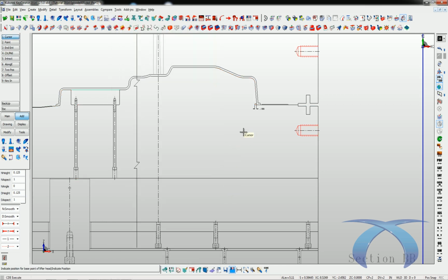So then all I want to do is give a general area where I want the bottom of that lifter to be, right? I can use my snap if I want to make sure things are nominal. It's totally up to me how I want to do that. Then once I'm happy with my location, I just push OK. And then which direction is my rod going in? Is the rod going in this direction, or this direction? So it's going in this direction, so I just place my cursor over to the right.